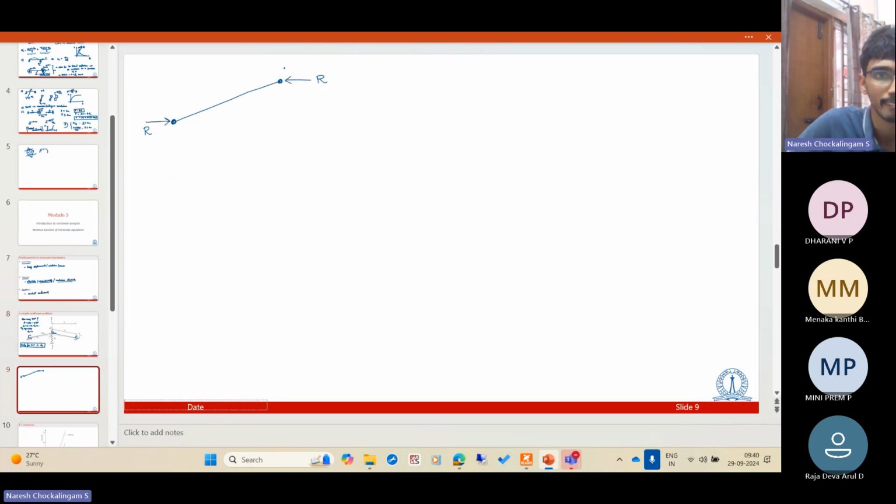So you apply a force F here, and you have a spring force. Let us call it Fs on half of the structure, so on the full structure it will be 2Fs. So what is the reaction here? F also. No, it's F minus Fs. You have F downwards, you have Fs acting upwards. So the net vertical force is F minus Fs downwards. So this has to be F minus Fs. Okay, so this is the system we have.